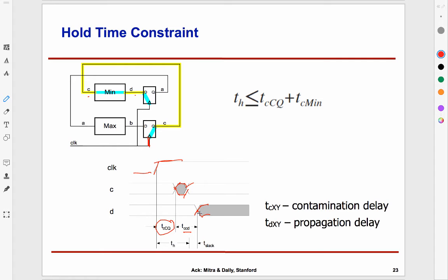And remember, our flip-flops also have a hold time requirement. So this clock edge out here has a hold time requirement. The same clock edge, when it appeared out here, requires that D should not change for a period TH after the clock tick. So what if TH was such that it was more than this point? That is, D begins to change, because I'm looking at how rapidly D can change, and maybe D changes too quickly. I'm still in the hold period, and that would be a bad thing.